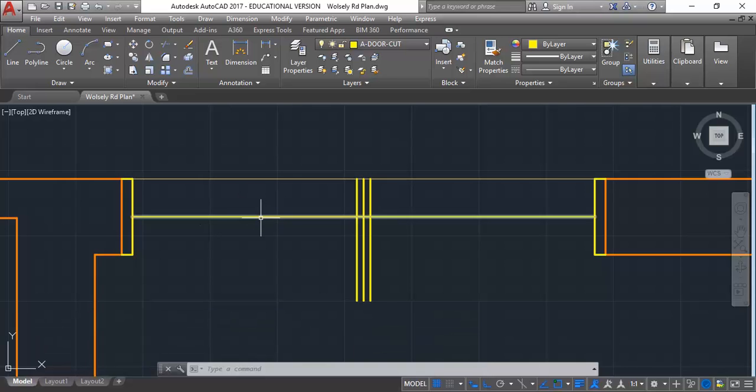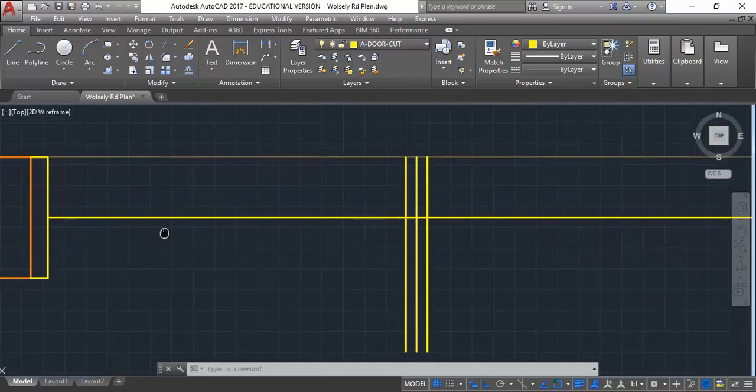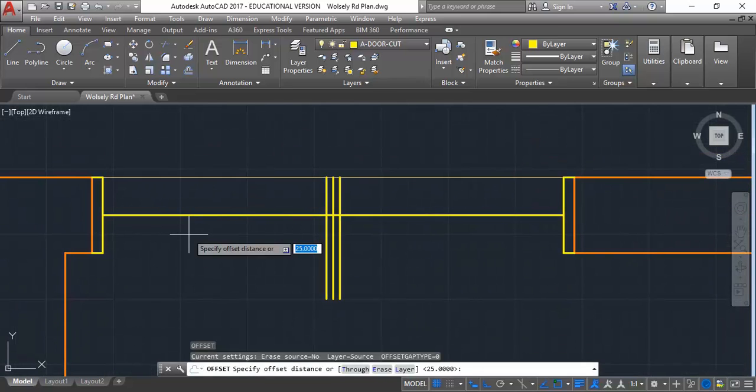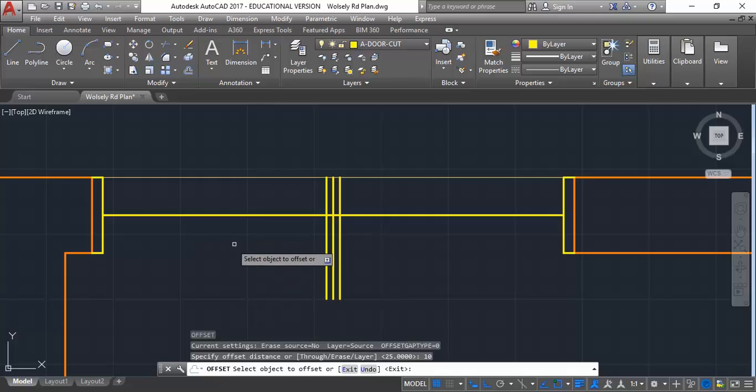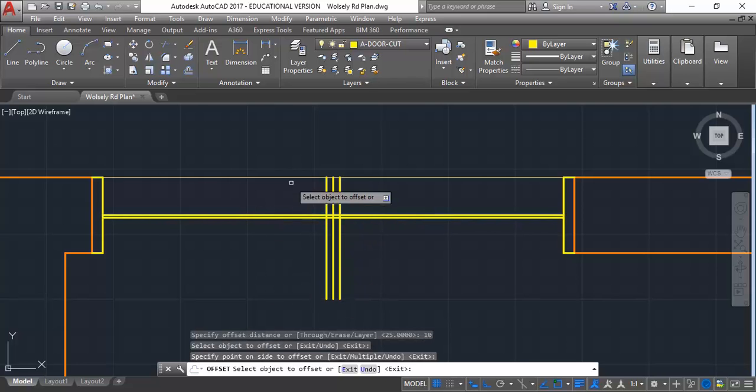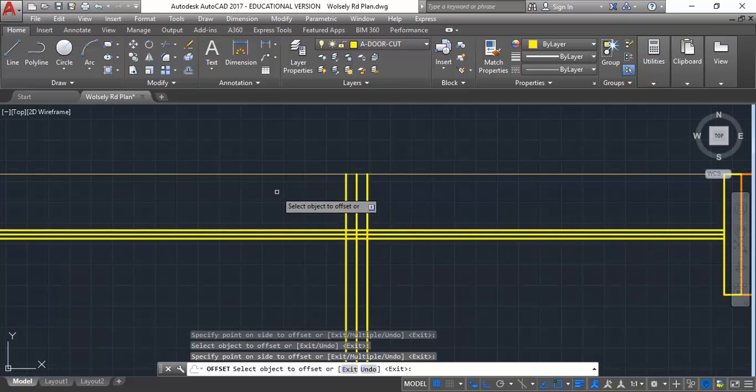Okay, so then I'm going to make the thickness 40mm, just like the jambs. But then I want a gap between these panels that I might just make 10mm. This is really just a graphical set out. In reality, they'd be touching, but we just want to have them showing with a gap between them. I'm just offsetting 10mm above and below that centre line.